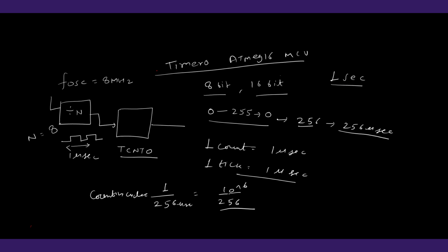Okay. Now the next question is, how do we check the end of the counting cycle? That can be done using the timer overflow flag. So we can check the timer overflow flag to check the end of the counting cycle.